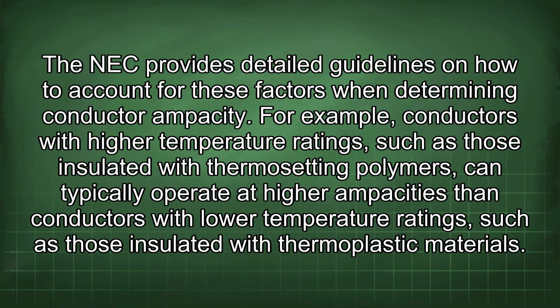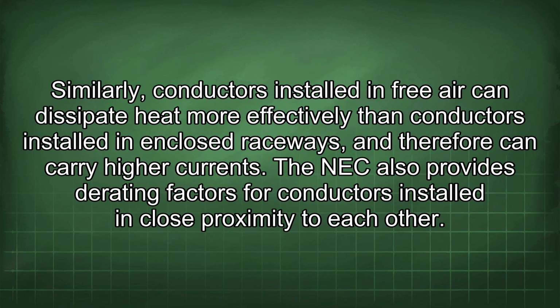For example, conductors with higher temperature ratings, such as those insulated with thermoset polymers, can typically operate at higher ampacities than conductors with lower temperature ratings, such as those insulated with thermoplastic materials. Similarly, conductors installed in free air can dissipate heat more effectively than conductors installed in enclosed raceways, and therefore can carry higher currents. The NEC also provides derating factors for conductors installed in close proximity to each other.